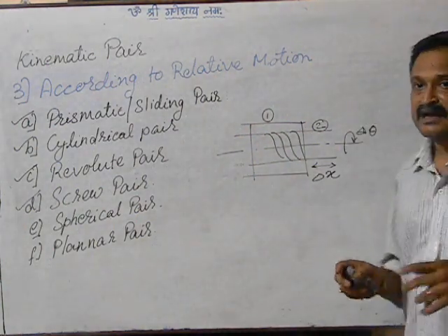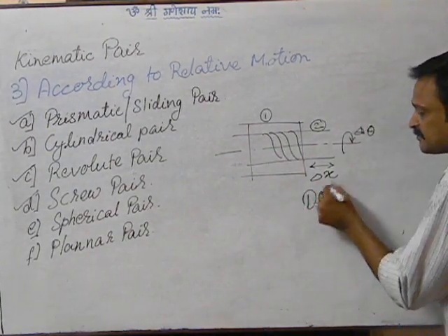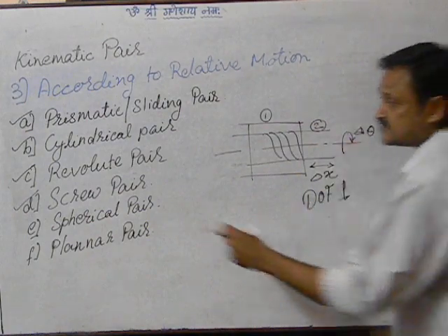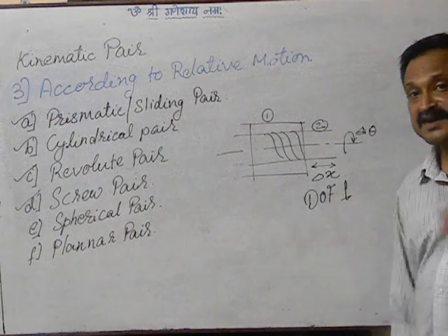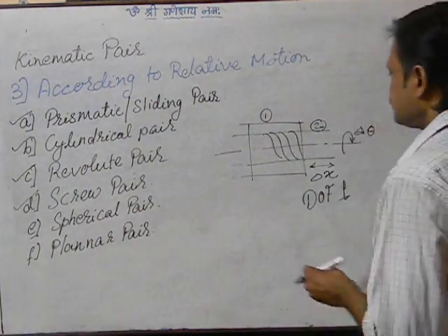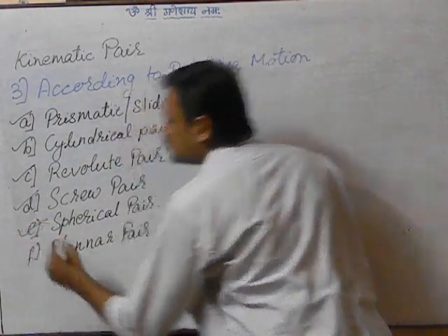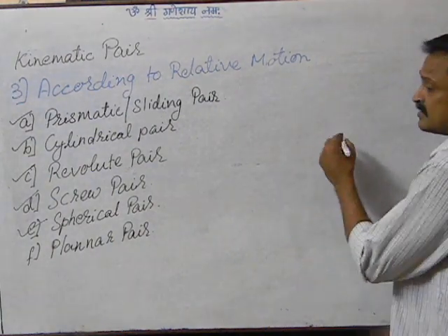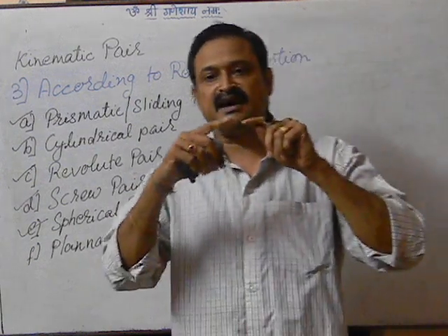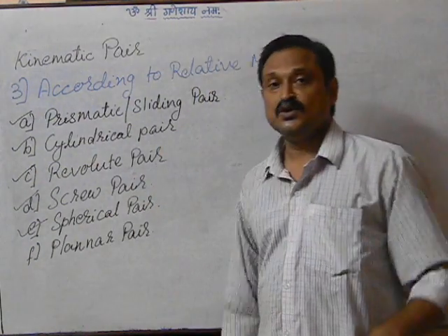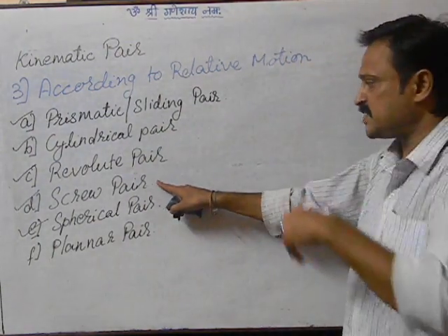So though apparently we see two motions in this link, the degree of freedom of a screw pair, which is also called a helical pair, is 1. Fine. Then we move on to the next, which is a spherical pair. Now, screw pair has a pitch and surface contact, so that will come into the lower pairs classification, and we call them closed pairs.